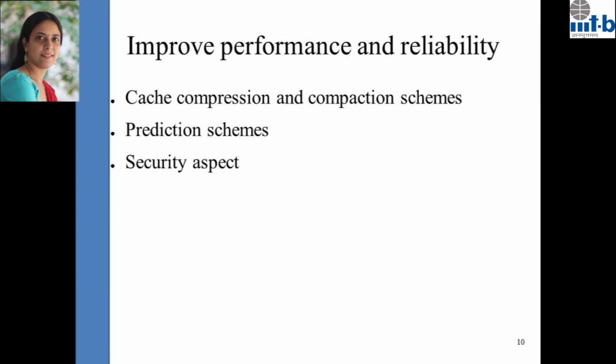The second topic is, we want to keep improving the performance of the processor. So what does a processor do? It just keeps executing instructions, right? So for example, if we want to do an A is equal to B plus C kind of an instruction, that is a very high level program definition as per our understanding. Now that gets translated to some kind of an assembly instruction. Let's say we are using an Intel x86 processor. So that will get translated to some kind of an add instruction inside the processor, right? So now the processor is busy executing a lot of instructions. You'll have a sequence of instructions, and we want to keep executing these instructions really fast. Fast in the sense, one per clock cycle, right?